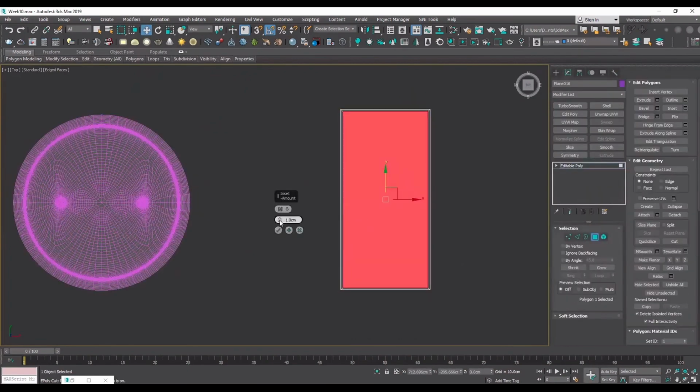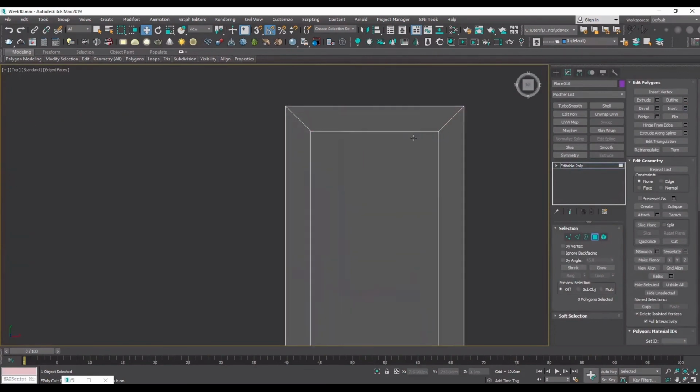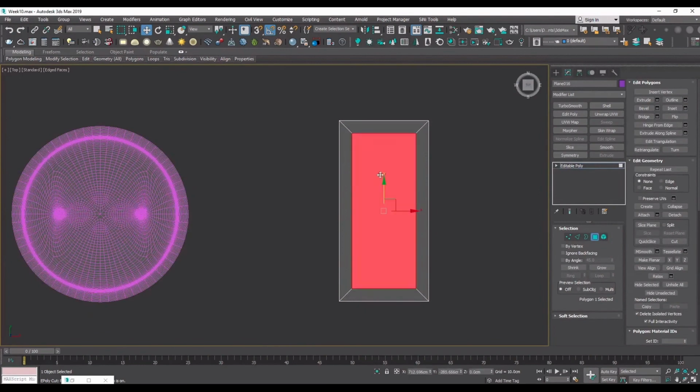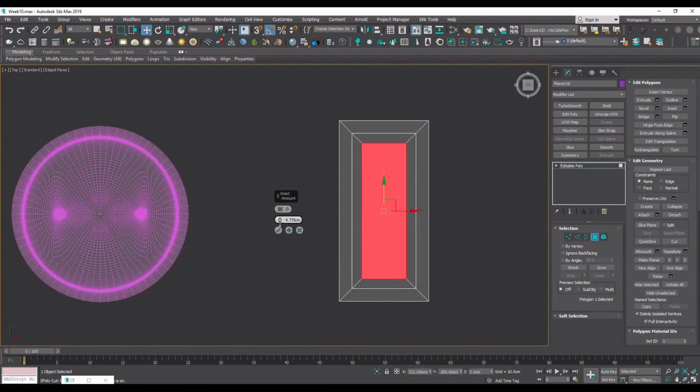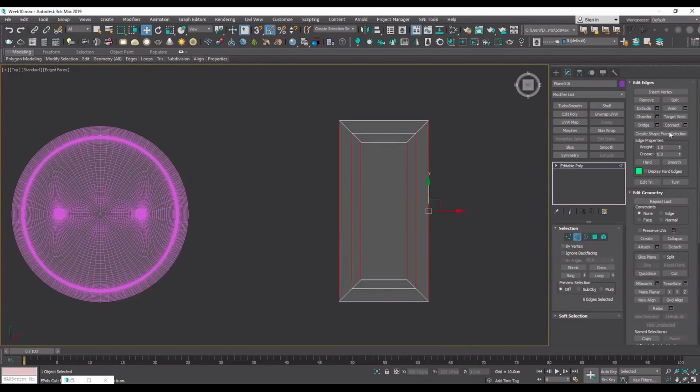Now, I want to get an inner inset from our mesh to the inside. Then, again, repeat the operation like this. I will explain why I did the operation again in just a second. For now, I create an edge loop on each side using the connect command and add our octagon with the n-gon primitive.